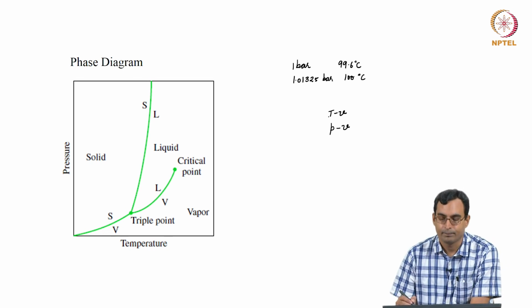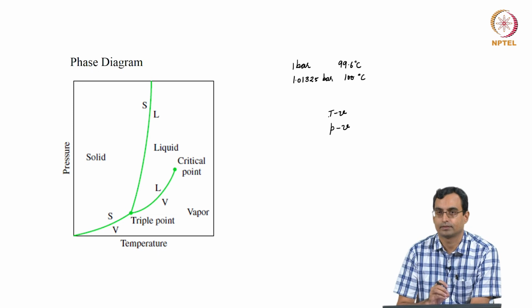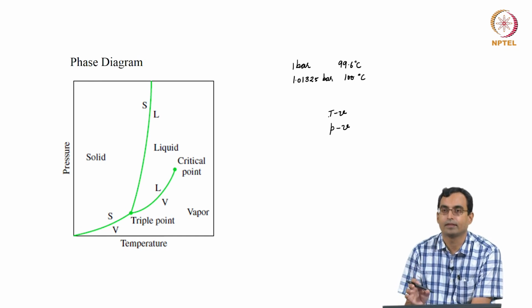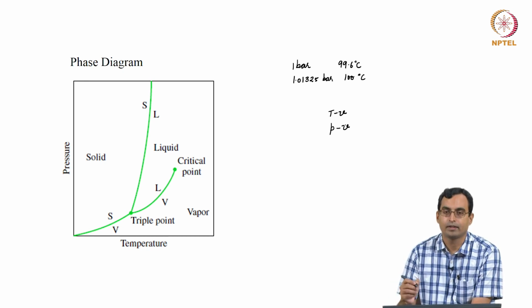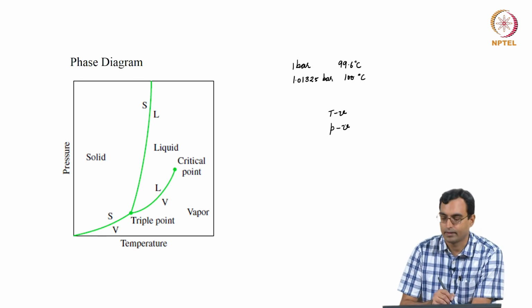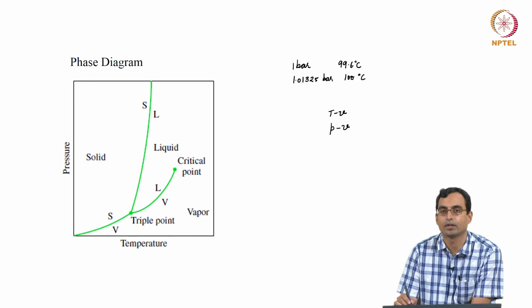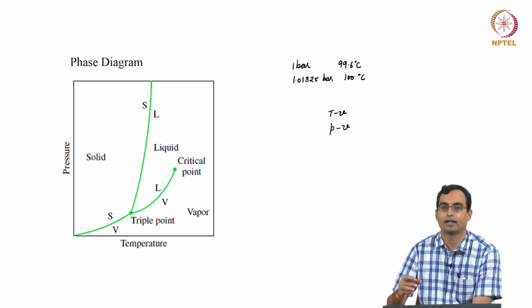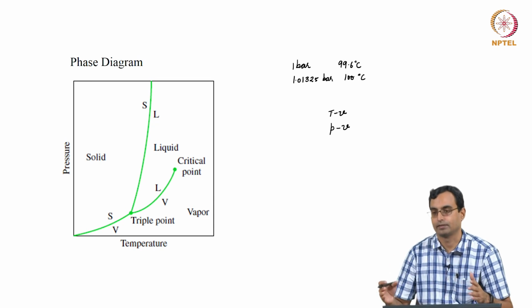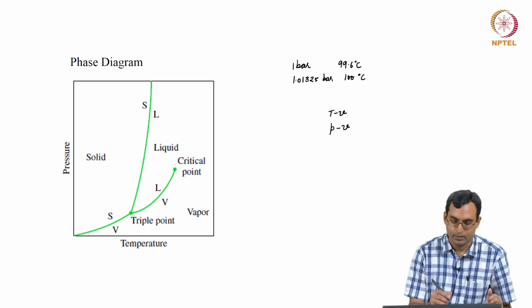On a P and T diagram, what we see is that during the conversion, the pressure and temperature are constant, or at least they are related, they are dependent on each other. So, if I keep the pressure constant, the temperature is constant. So, I do not see the two-phase region in the same way in which I can see it on a TV or a PV diagram. Here, once it reaches the boiling point, that point is just a point on this diagram, because I can only plot 1 bar and 99.6. That is just one point. Whereas, in the case of T and V, if I was at the boiling point, I can have the same temperature and different specific volumes as conversion takes place. So, we had a region which represented boiling over there, whereas only a point represents boiling here.